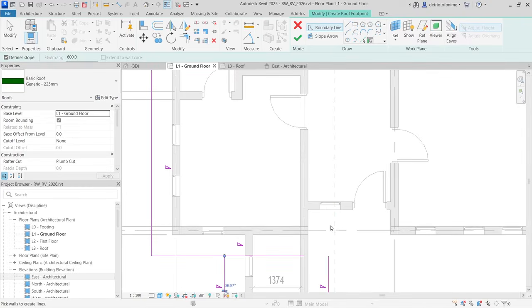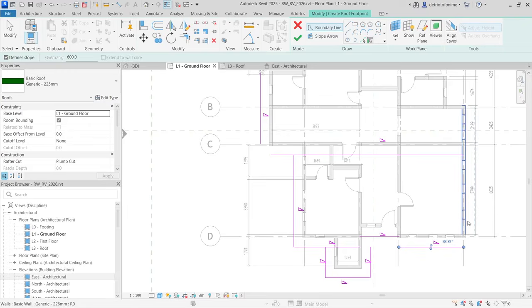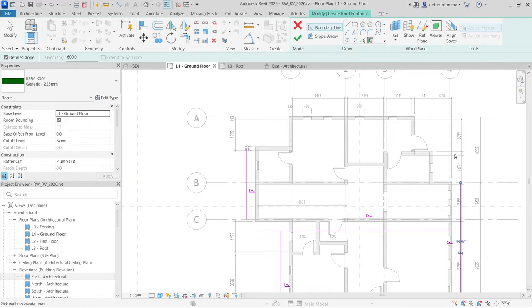So now that we have this, there's also another veranda here. Go ahead and select this roof and select this part of the roof as well. Like this one, we still have to manually go around it and draw and edit. So select this, like this, and this, then this wall, and this wall, and this wall. We're trying to do a gable roof, so now we can go about editing the roof itself.